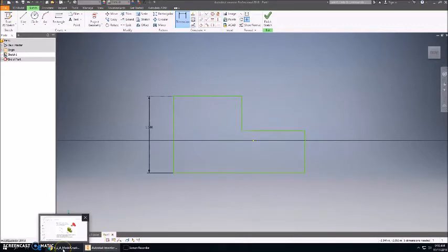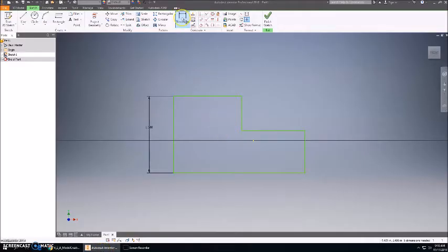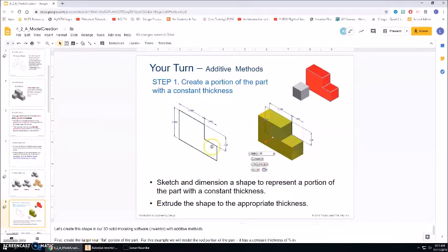Now by pushing on the center wheel of the mouse, I can get that pan tool, which allows me to recenter. Coming back over here, I now need to have 1.5 across this edge, and then 2 3/4 of an inch dimensions. So I'm going to follow the same procedure: click on the dimension tool, hover over the line, drag and pull away, input 1.5. This line needs to go to 0.75. We have 0.75 here. And then I believe my last one, let me double check. Okay, we can assume that this is also 0.75 because we've dimensioned everything else.